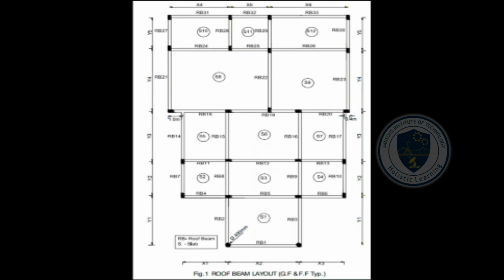plinth beam. Lintel beam layout. This drawing represents the dimensions, position and section of lintel beam and the details of reinforcement in lintel beam. Roof beam and shuttering layout. This drawing represents the details of reinforcement of roof beam, section and shuttering details.